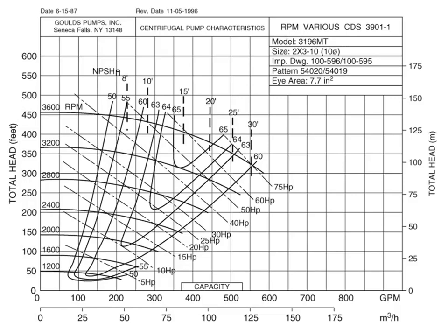All right. I mentioned previously that there are these manufacturer-provided pump curves that talk about performance, and there are a couple of elements I wanted to show you on this pump curve. First of all, the y-axis is showing the total head that a pump is able to produce, and you see that as the flow rate increases, the total head decreases.